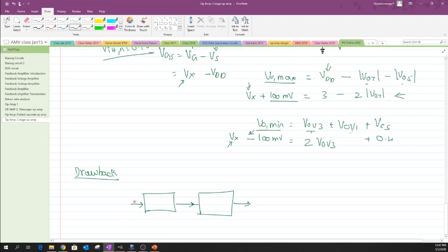And when we have too many poles in the transfer function, whenever we try to put these op amps in negative feedback, they tend to step into what is known as an unstable system. There are specific values of beta that it can support, but when you try to have a feedback network where beta is equal to 1, or a unity gain feedback, then having too many stages in an op amp will end up resulting in what is known as an unstable system.